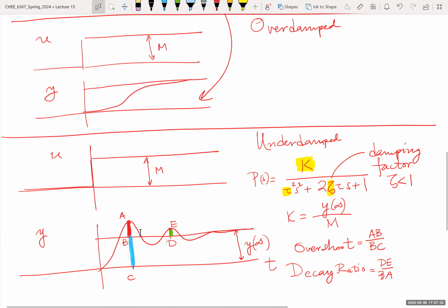And again, let me remind you one more time. The Ziegler-Nichols tuning rules create closed loops which exhibit higher order dynamics with decay ratio about 1/4. Green to red for the closed loop is about 1/4. Okay. But here, for identification purposes, we can use either one to do the following.